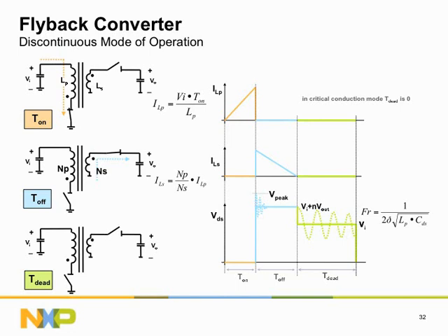The voltage waveform as shown in the lower graph is an idealized waveform. The actual waveform would only be such if the operation of the transformer, or better, set of coupled inductors, would be ideal. And in a practical situation with a real transformer, that is not possible, of course. With a real transformer, we will see some voltage ringing when the secondary stroke begins and after the secondary stroke ends. The damped voltage oscillation, or ringing as we usually call it, at the beginning of the secondary stroke is caused by the leakage inductance of the transformer. The ringing will cause the maximum voltage across the primary switch to rise above VI plus NV out. The higher the leakage inductance, the higher the peak voltage, shown as V peak in the graph, will be. When selecting a primary switch, the voltage rating must be such that it can easily withstand this V peak voltage.